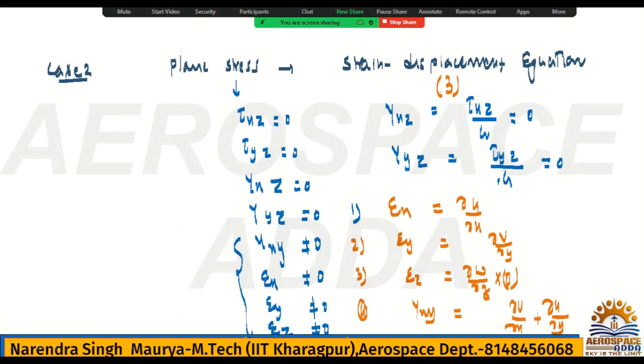Sir, 2 na, see, xz and yz. This part will be there, this part will be there, and this part will be there. This is not possible because we are talking plane stress. So I'm saying the strain displacement equation is not possible. That third equation is not possible because it's a plane stress condition.